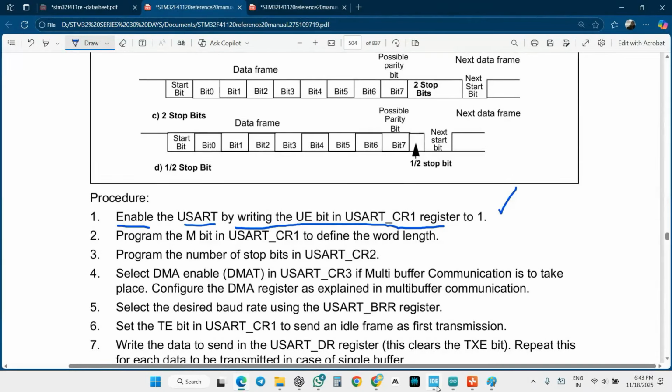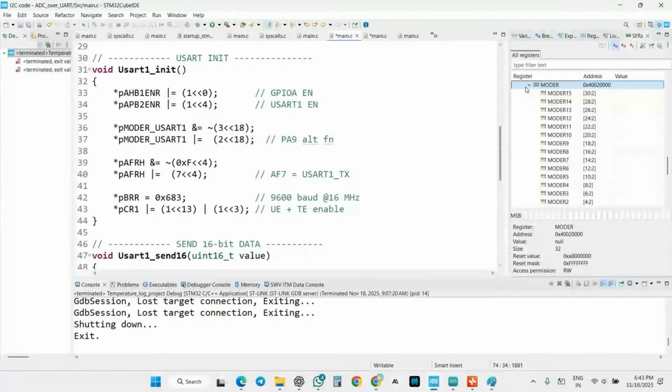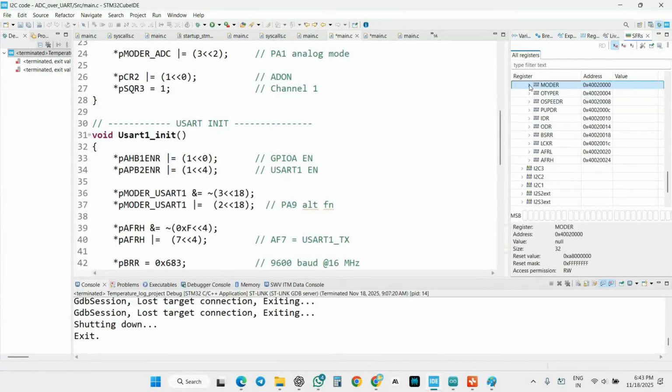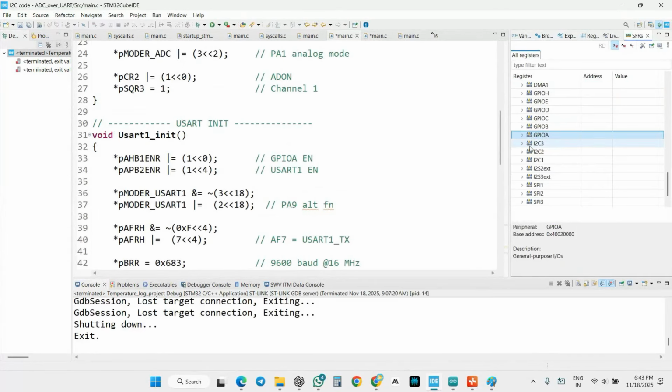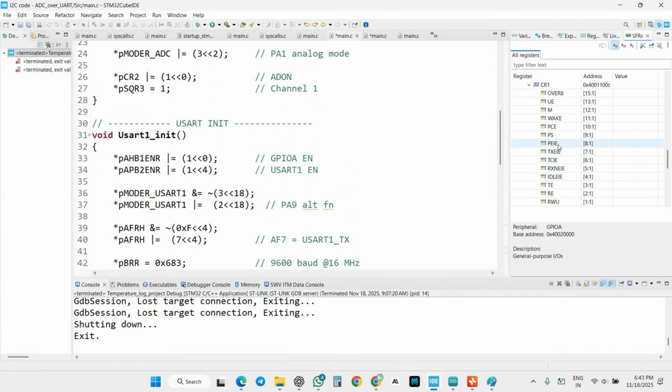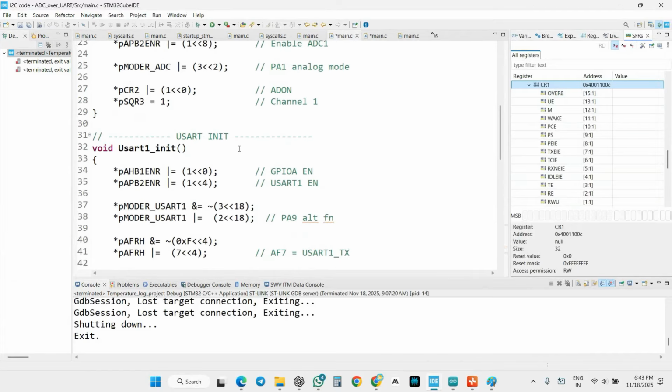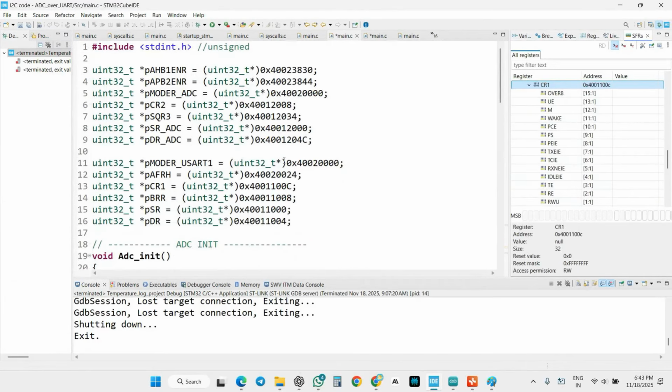And we have done this one. So here, if I'm not telling you this address is going to be right, because same thing, guys, if you are going to use, for example, UART1, in this UART1 you are going to use CR1 and the UE bit. The UE bit is going to be enabled. If you're going to enable or disable any bit, you have to write the address first. It is a very, very important thing. So same procedure, copy, copy, copy.